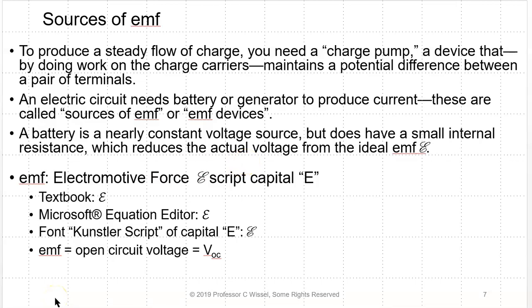The EMF is the electromotive force, and it's typically written with a script capital E. There are many different ways that you might see it written in various places. The big thing to remember is that the EMF is the open circuit voltage, otherwise known as VOC. It is also called the no-load voltage, and it's the voltage that you measure across the terminals of a battery that is not connected to anything else, or that does not have a current going through it.